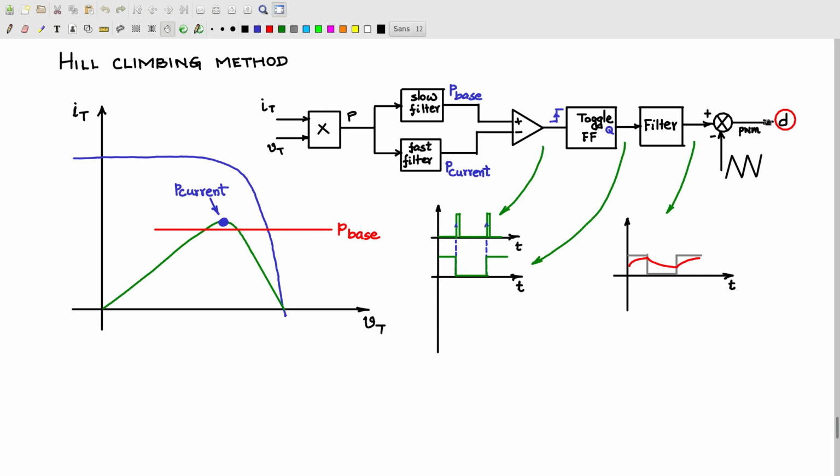converter. The DC-DC converter we will choose is the buck boost converter because it is able to operate on the entire IV characteristic. So let us go to SPICE and see how we will be able to simulate all these blocks and integrate it with the operation of the buck boost converter interfaced with the PV source.